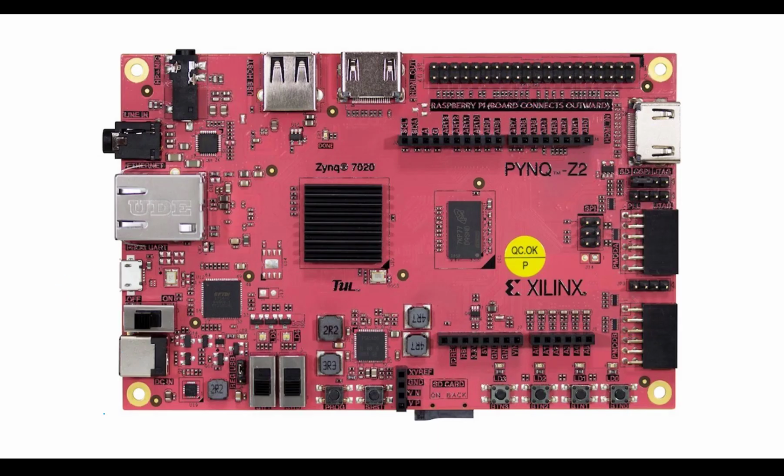So if we look at the pink board, we already know that the pink board has two slide switches which can be used for inputs. It has 4 of these push buttons which can also be used for inputs, and it has these 4 LEDs, right? So in the scope of this experiment, what we are hoping is that we will give inputs on these 4 buttons. Okay? So A3, A2, A1 and A0. We are hoping that it is in this order from most significant bit to least significant bit that we will give inputs.